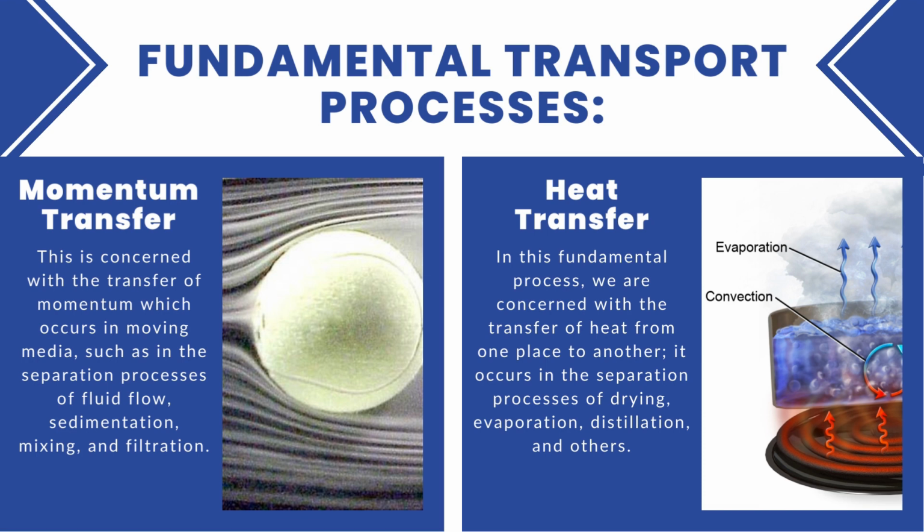Moving on with the second transport process, that is heat transfer. When there is a difference in temperature among the medium, heat transfer takes place. The heat flows from higher temperature to lower one. The more the difference, or we can say the increased gradient, the better the heat transfer. The temperature difference is the driving force for the heat flow. Application of this type of transfer is observed mostly in separation operations of drying, evaporation, distillation and many others.